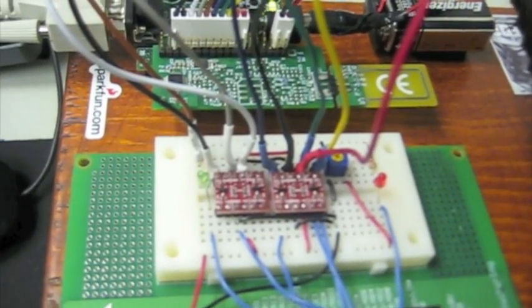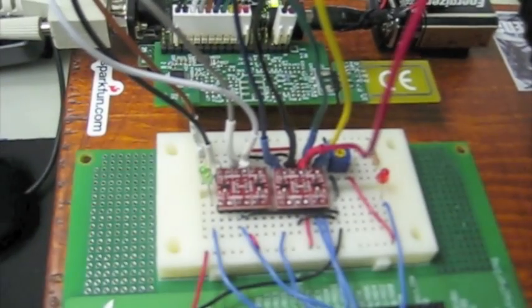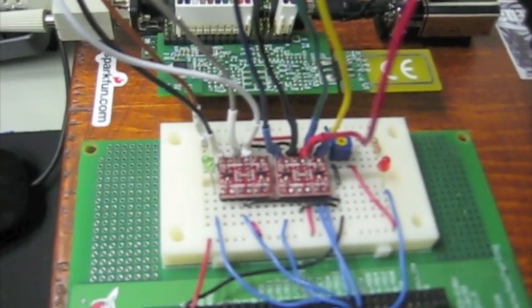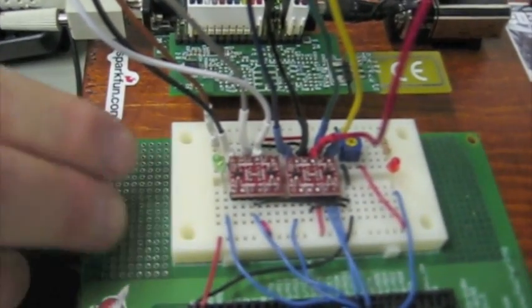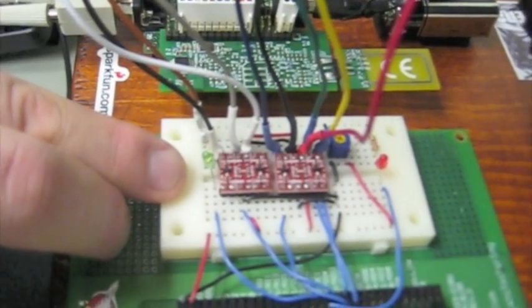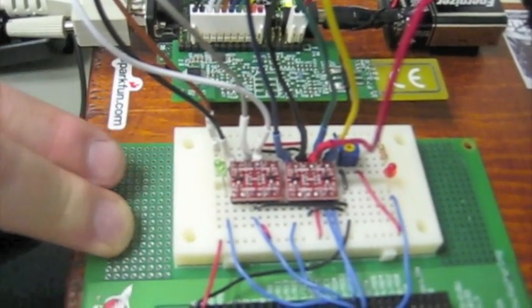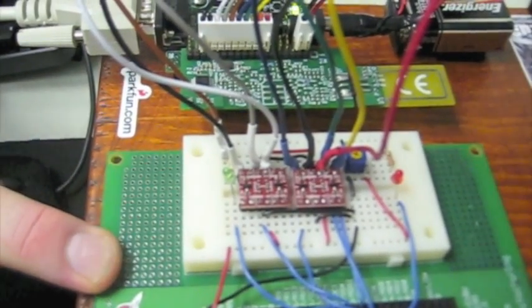In step 3, we will continue on by showing that the data is being received by the receiver and passed through the HC11 through the SPI. We have connected inline logic converters that step up our voltage supply, which is 3.3 volts in the RF, into our HC11 of 5 volts.